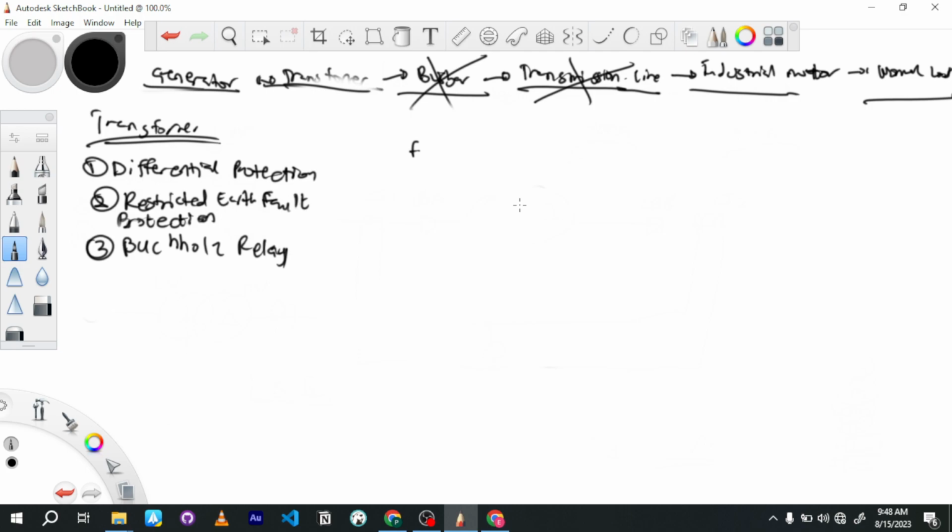That's the first way. The second way is that, for example, only some part of the oil is being heated. It's like what happens in glass annealing: some part is heated, some part is not, and then the glass breaks because there's so much stress on it. So you can have localized heating, which will decompose the oil into gas. Or the failure in the winding insulation will result in arcs, and the arcs themselves would decompose the oil into hydrogen and methane. These are all gases in the system.